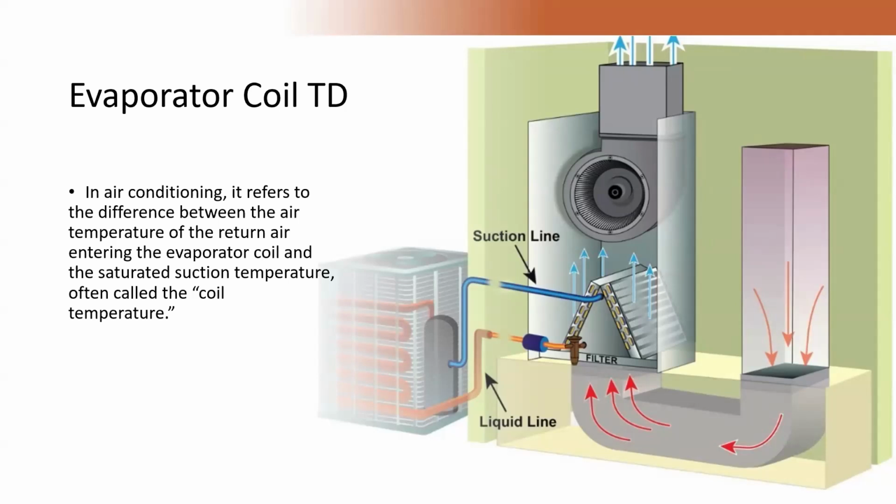And then we have mechanical devices. We have electronic devices that are metering that refrigerant flow. Its job is to maintain superheat in that coil. And as we looked at earlier, higher superheat, going to be less full in that evap coil. Lower superheat, more full that coil is. That's the job of the metering device. It is going to try to manage like a police officer with a traffic sign in the middle of New York. It's trying to manage all sorts of things at one time: refrigerant flow and airflow.